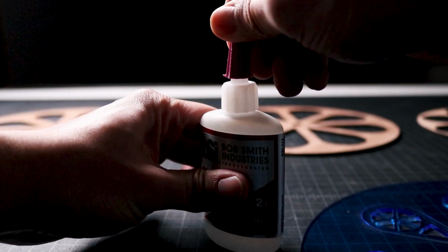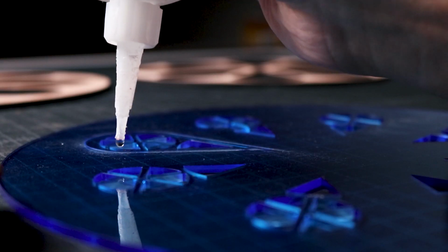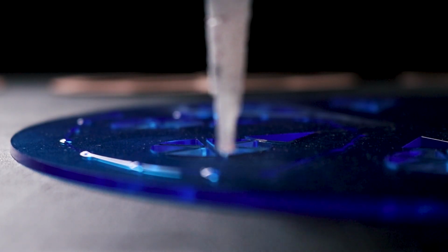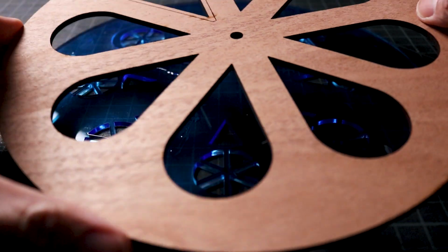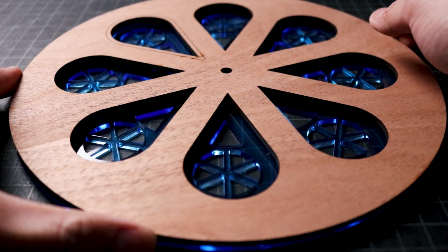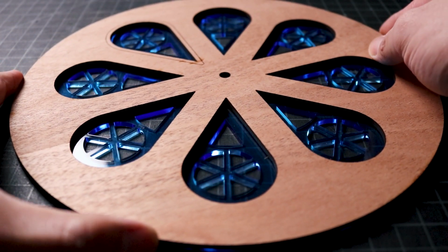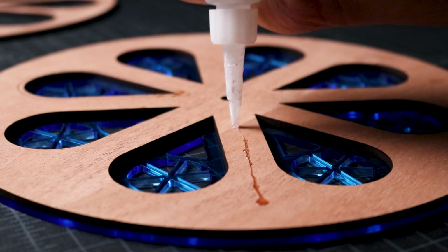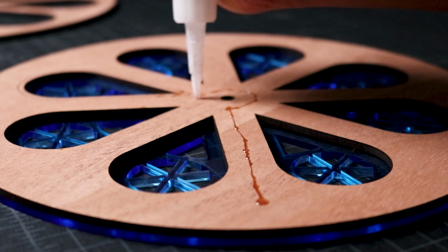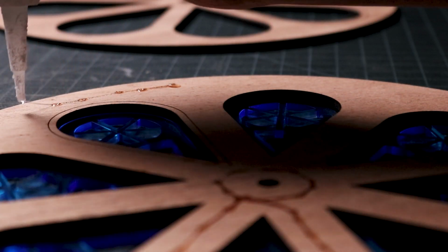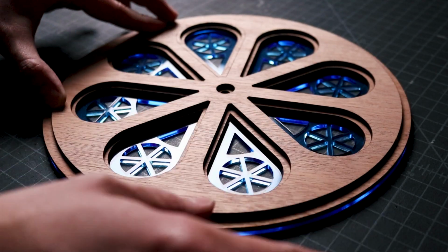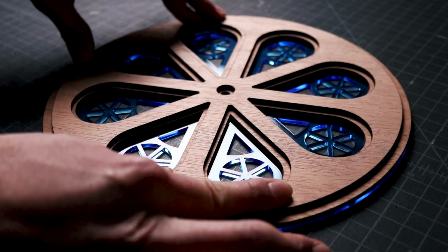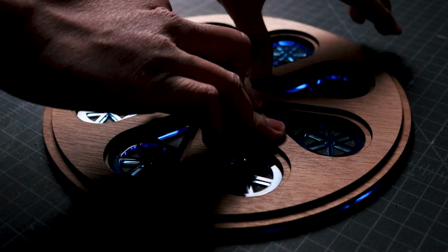I brought over my super glue and applied it to the top of the blue acrylic where the next layer would be attached. Then I brought over the layer above, aligned the cutout with the engraved line that I put around one of the cutouts, and pushed it into place. The engraved line won't be seen by anyone since it's the perfect outline of the cutout for the layer above, but it helps us speed up the process of aligning every layer. Over the years, finding these little tricks have really sped up my process and made the assembly a lot easier.